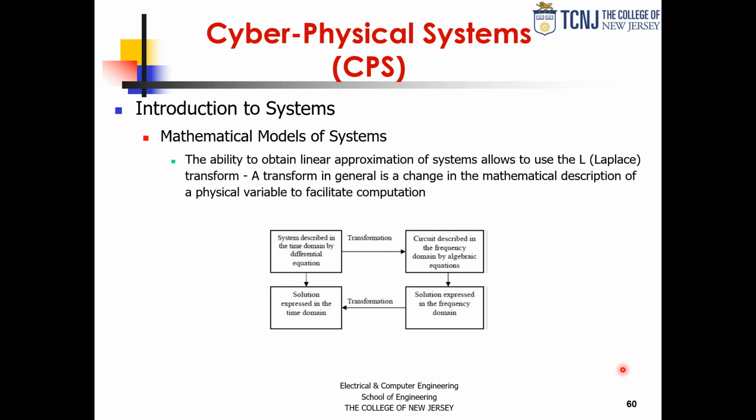Okay? So you could come up with a very nice filter to reject a specific frequency, for example, which is the opposite. Instead of making everything else zero and keeping a band, you make a band zero and keep everything else. So a rejection type filter, let's say for rejecting 60 hertz, which is in the environment for medical applications.